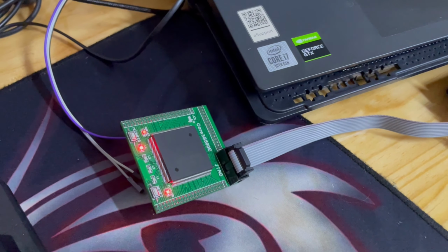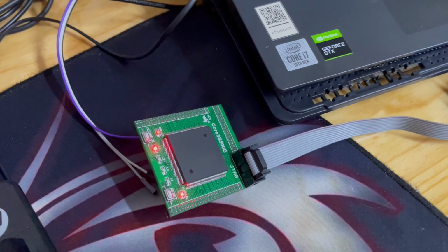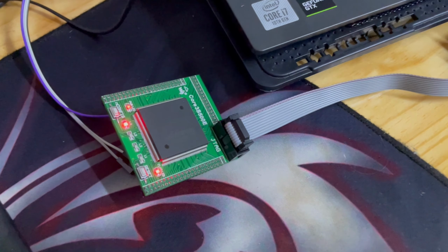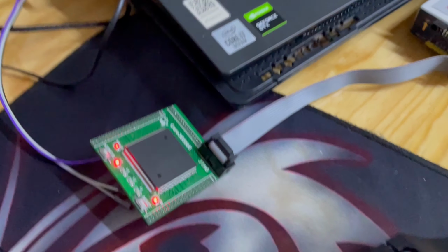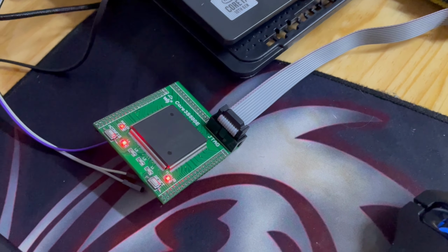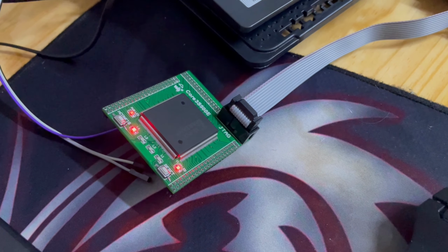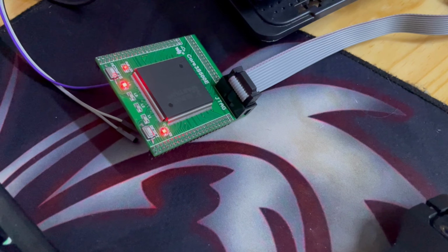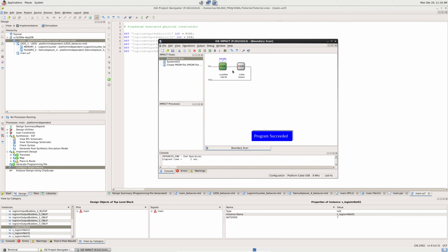And this is not a problem on FPGAs really, this is a problem in anything electronic really. When you have an input button or a switch or anything that needs to make contact, you basically always have this bouncing problem. So let me show you what this bouncing problem actually is. So I'm just going to open up Paint here just to demonstrate this.